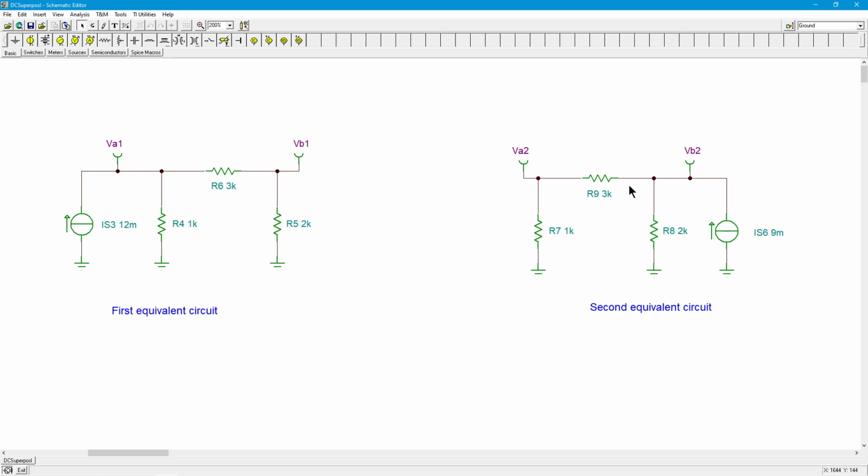That'll give us 12 volts. And then the balance of 3, right? Yeah, 6, 9. So that would be 3 down through there. That would also give us 12 volts as expected. Then we could take that 12 volts, do a little divider, just like we did over here between the 3K and the 1K, right? So that's 1K over 4K, 1/4 of that potential, right? That was 12 volts. So 1/4 of that would be 3 volts. So now I take those pieces and we add them together, right? Take this voltage, add them together, take this voltage and this voltage, add them together, all right?